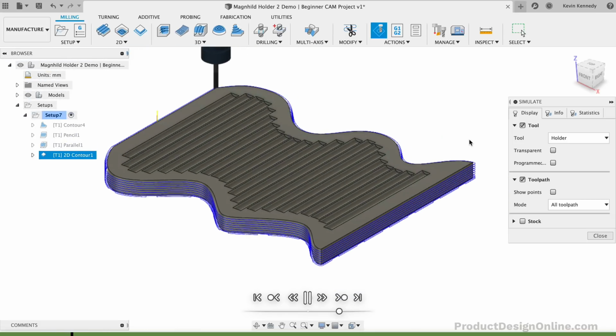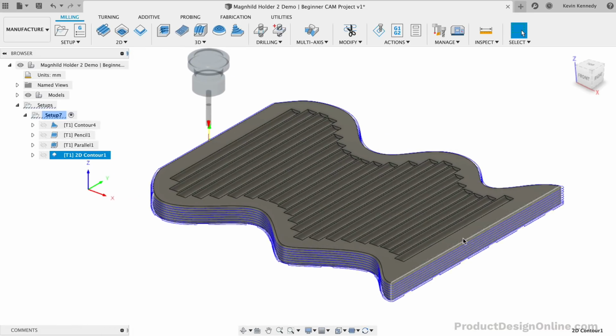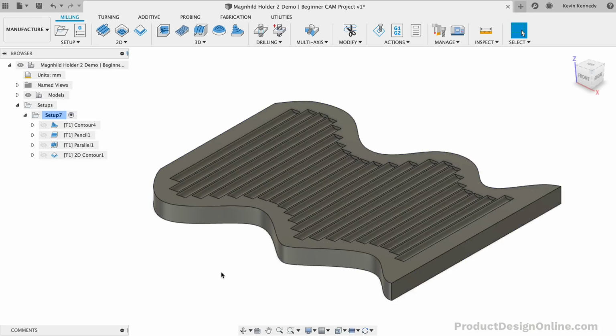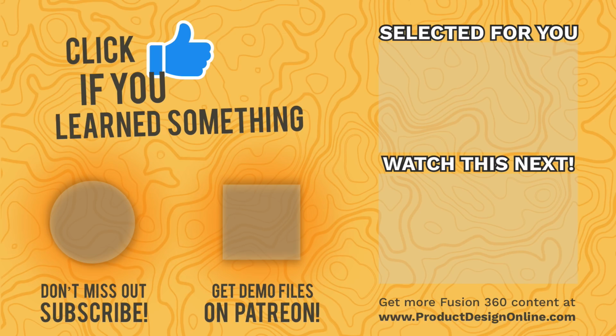To summarize this video, we looked at creating a sculpture piece by tracing a reference image while creating a 2D sketch with some simple sketch geometry. We then turned the 2D sketch into a 3D body, which lets us further define the shape by cutting away some of the 3D material. Once the design was finalized, we were able to set up some simple toolpaths in the manufacturer workspace. That would allow us to mill the wood piece on a CNC machine. This digital fabrication workflow can be followed to create endless designs, with the only limitation being your creativity.